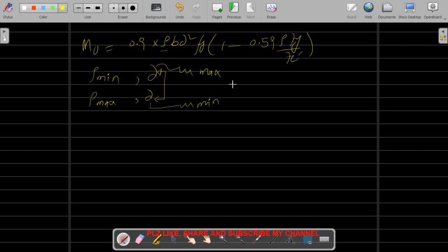This maximum and minimum values means that if we increase the depth from this value, it will cause the ductility check to fail, because we will use this ductility check that rho provided will be greater than rho minimum, and it should be less than rho max. We know about this check. We did this in lecture 01 and in various examples.